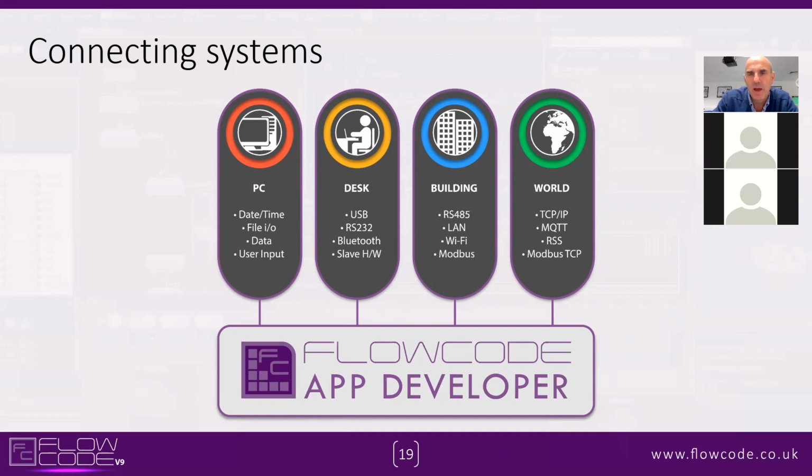In terms of input-output, though, which is our main goal, if you like, we think about desk-based systems that have USB, RS-232, Bluetooth, and slave hardware devices. We think about building-based systems, which is the larger comms protocols with local area network, RS-485, Wi-Fi, and Modbus. And then we think about world-based systems,